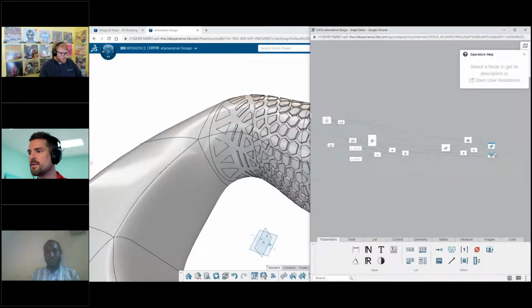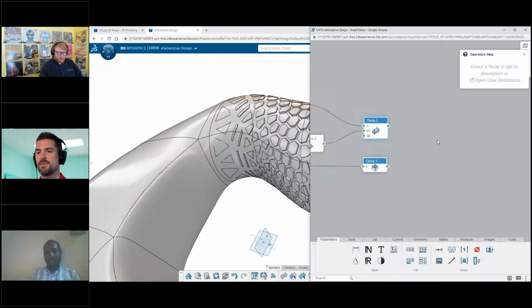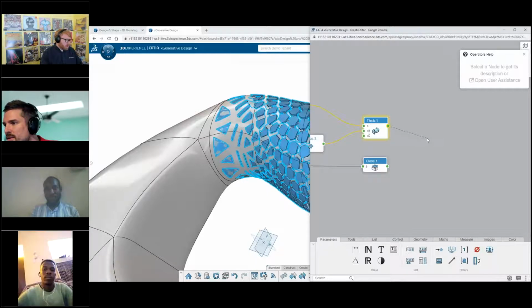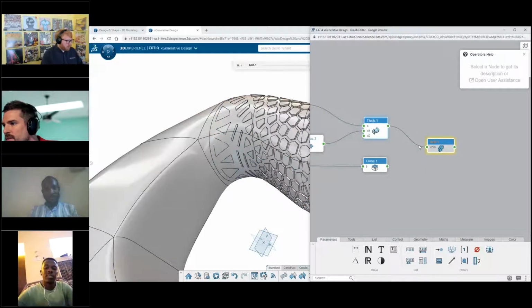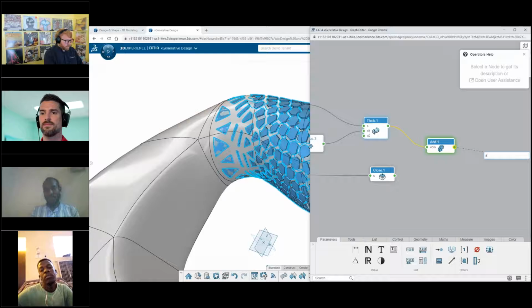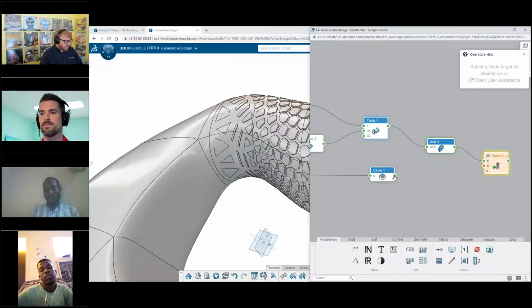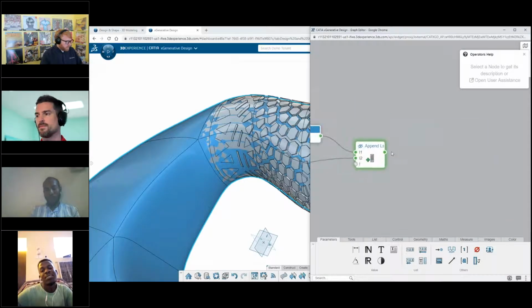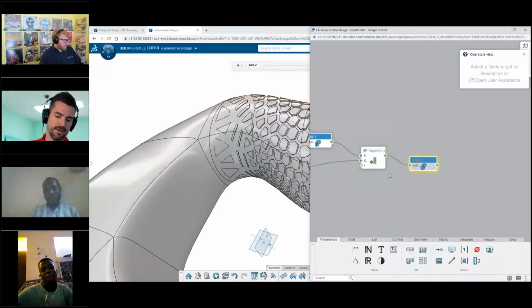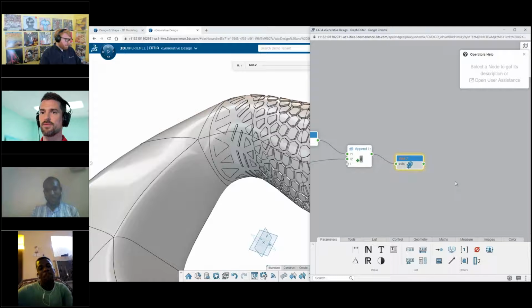Like Andrew and Jordan have been saying, with the quality of NURBS surfaces here, anyone involved in mold tooling can buy a CNC machine that's high quality enough that it will machine in geometry defects that you'll feel in your hand in the end product and that will require hand cleanup on the mold tooling. So if you're using tessellated geometry, that will show up in the final product and require rework. That would be a lot of rework.